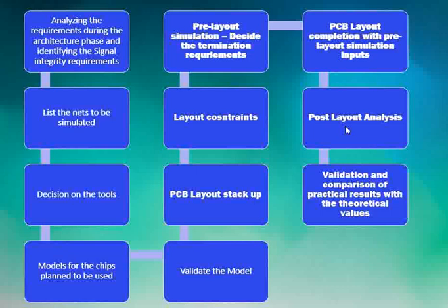layout. So there will be a few iterations between the layout engineer, schematic engineer, and the signal integrity engineer during the design phase, and it's a cycle where they come to a common conclusion based on the simulation results that yes, this timing looks good, and the signal looks good, integrity has been maintained for the signal, and then they release the PCB layout. Now the signal integrity engineer's role should not just stop with this.